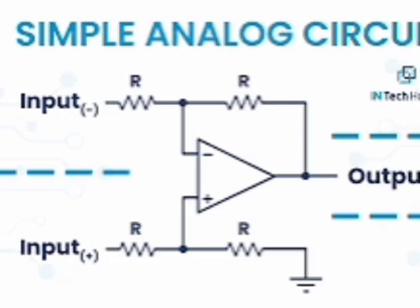Number of diodes required: half wave rectifier is 1, center tap based full wave rectifier is 2, bridge circuit based full wave rectifier is 4. Form factor of half wave rectifier is pi by 2. Form factor of center tap based full wave rectifier is 1.11. Form factor of bridge circuit based full wave rectifier is 1.11.